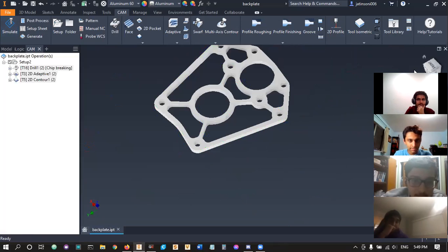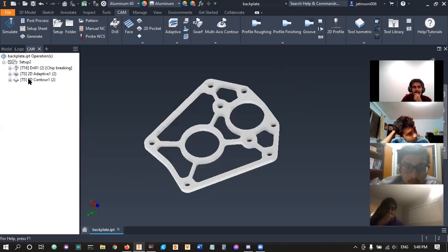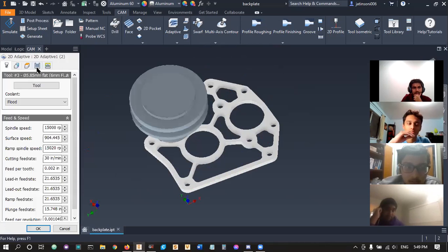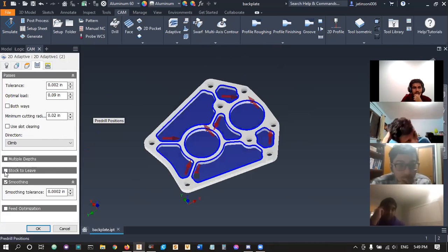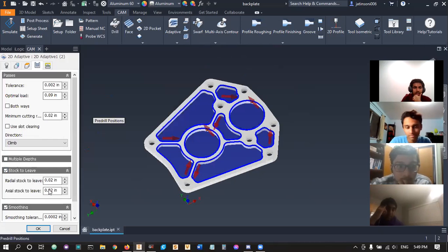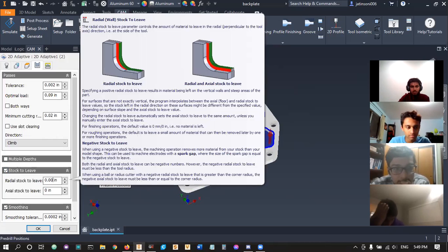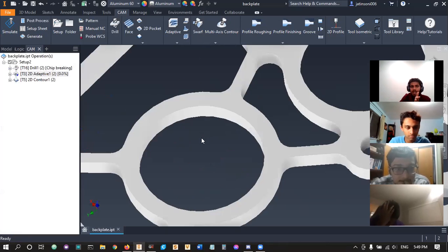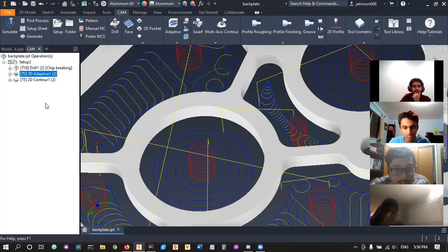So do you guys have questions in this portion? Do we still have to do the finishing contour? So the finishing contour is basically, remember in adaptive, we had this portion, stock to leave, so that you get higher quality, right? So axial means up and down an axis, and then radial is outwards, right? So we want to do radial, we want to leave 0.005. The adaptive will cut out a hole that's 1.12, and we need to do that final 5 thousandths.